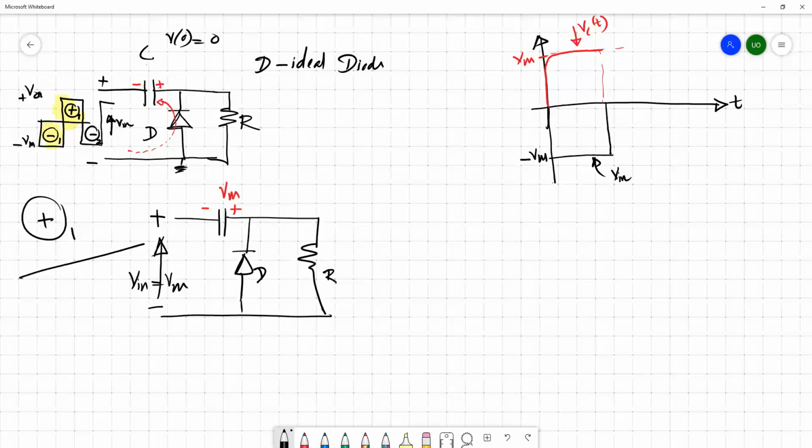If this diode is forward biased for this particular cycle also, then we can claim that the diode may act as a kind of short circuit element to facilitate this current. If the diode is reverse biased, we can argue that it acts as an open circuit element, so there won't be any current flow through the diode. So we'll see first whether this diode is forward or reverse. So this is your diode draw.